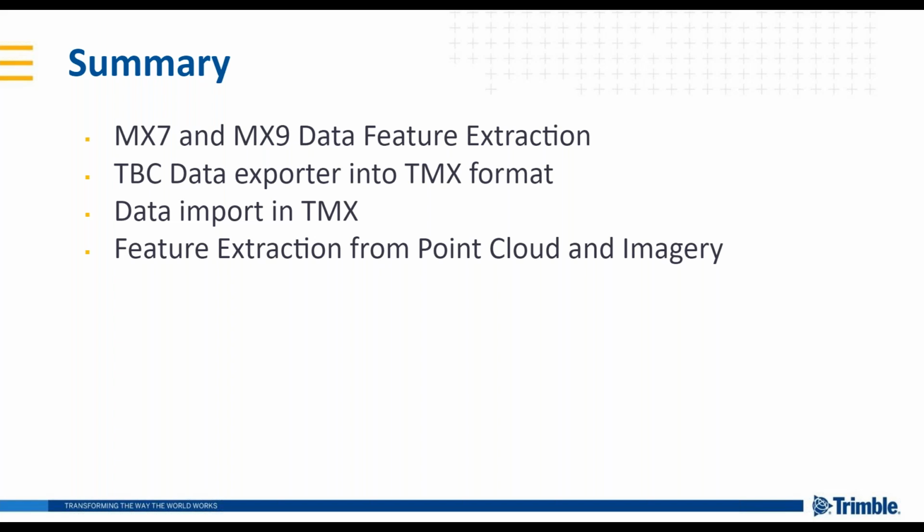Does this apply to GeoEd for the vector data? Yes, you could measure in any coordinate system that you like. Personally, I prefer for now to use UTM, but when I'm exporting my features, I could choose to export them in any corresponding coordinate system of my choice.